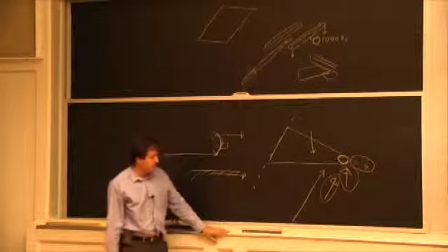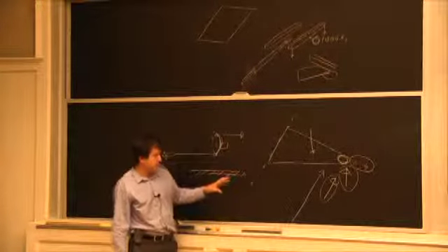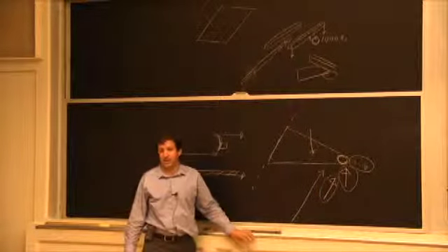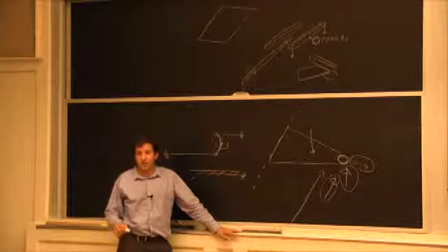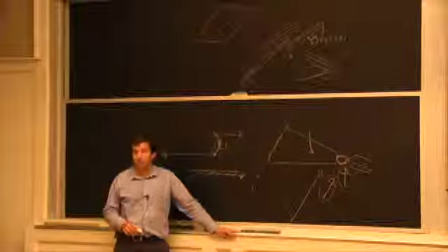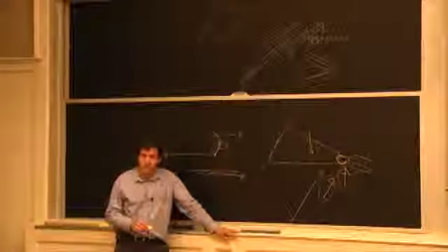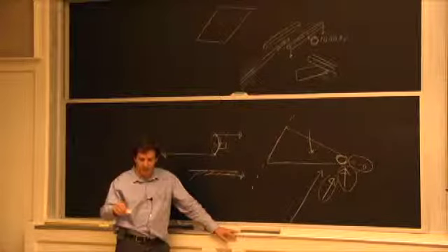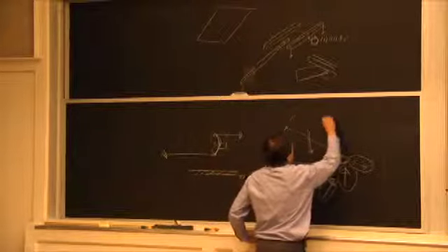Now, once they've taken all of this into account, if you go to fatigue for this, you don't have a safety factor of 4 anymore, because you've looked at it enough that you can tell it's not going to go much beyond your calculation. And it's the same for manufacturing. They make the welds in segments. So if you have a weld around a round member here,